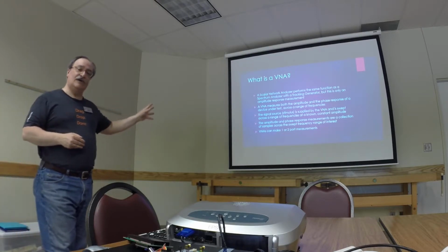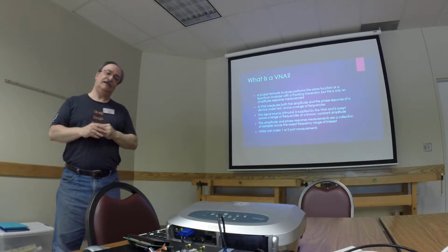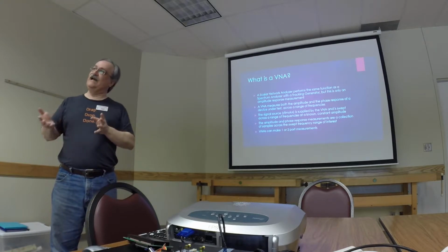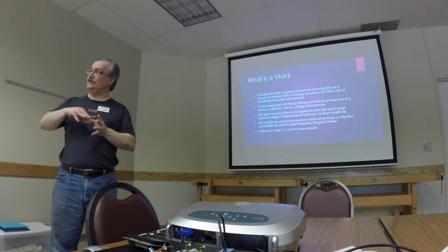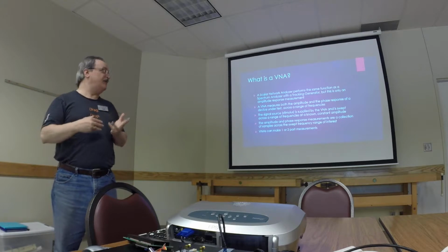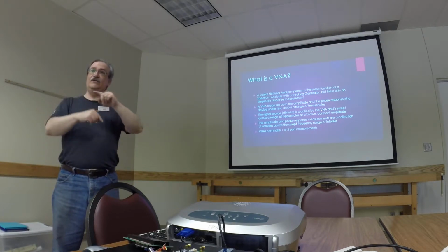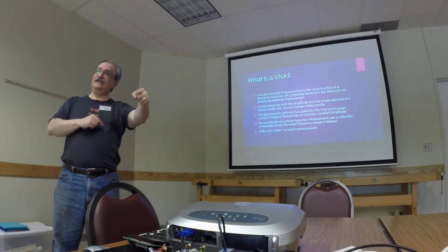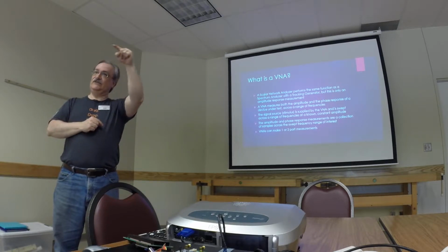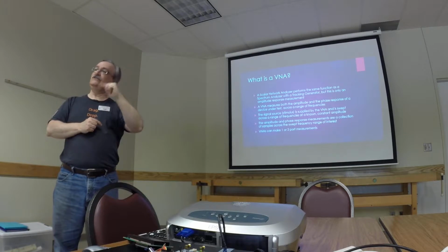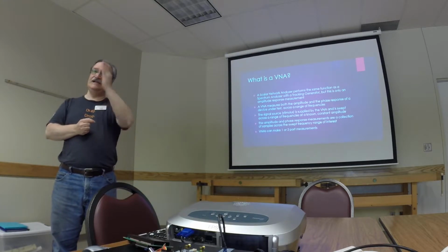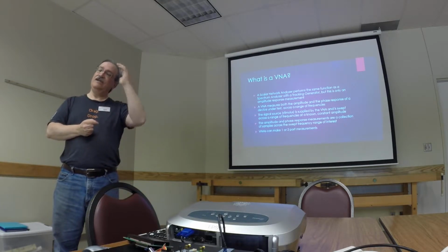A vector network analyzer, on the other hand, goes a little bit further because it adds phase into the picture. So not only are you making magnitude response measurements, the way you would to trace out the characteristic of a low-pass filter, for example, but you're also measuring phase at every point that you sample.